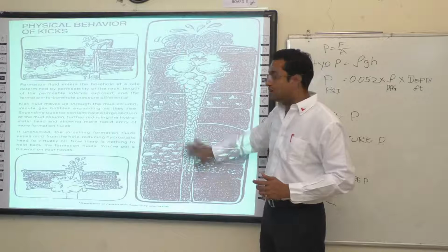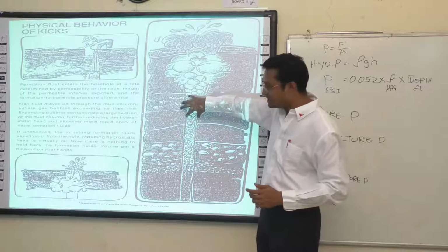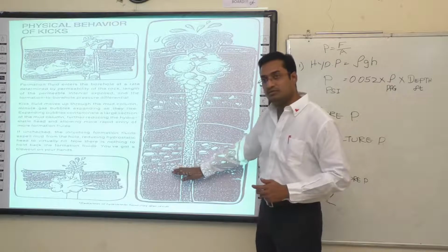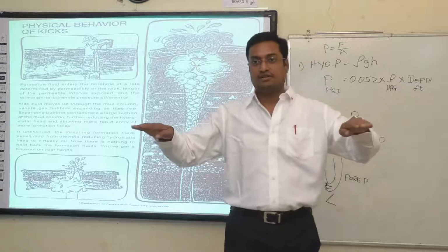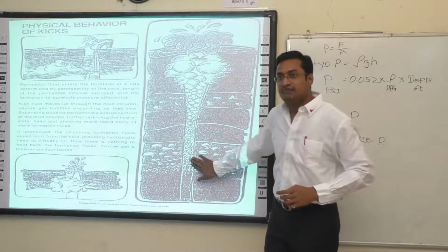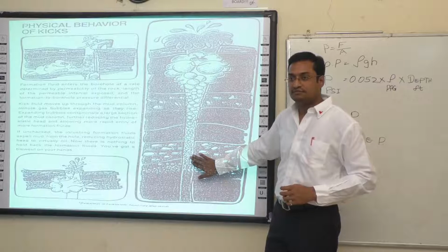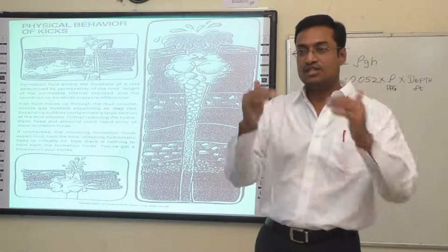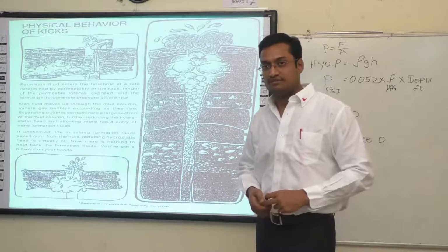The bottom hole pressure or the hydrostatic pressure will increase because the air bubble is coming up carrying the same pressure. When the air bubble comes up, this pressure plus the drilling fluid pressure will balance the formation, and it will go to overbalance condition. So it will stop further influx getting into the wellbore. It will control the kick by itself. That condition is called the stabilized condition. This condition has to be attained before you do any well control procedures.